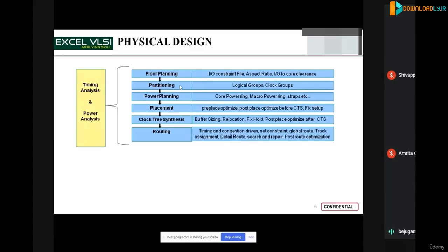So this is about the physical designing stage, and parallelly there are some other operations happening at each and every stage. At the power planning stage, as I told you, we need to do some power manipulations for the circuitry. So those power manipulations are nothing but we create some power rings. There might be some IPs like macros. A macro is nothing but an implemented logic or a pre-designed logic. We provide power rings for those modules if they are coming in my netlist, and some stripes for the gates that are coming and sitting in the placement stage.